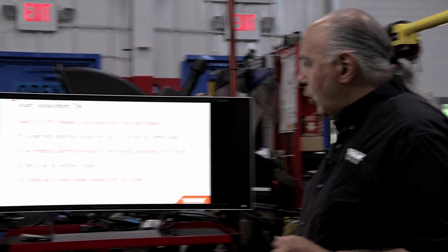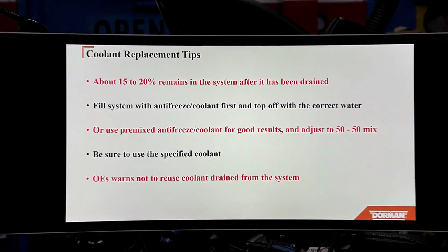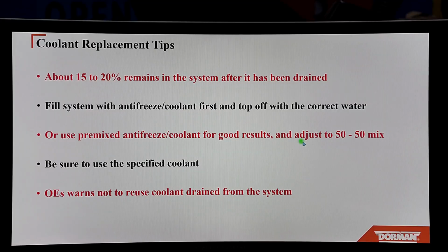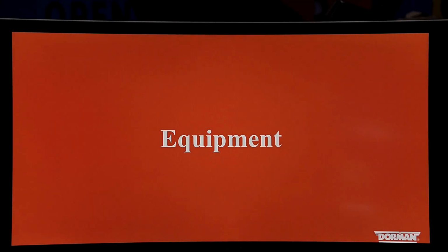They'll have the right water in there if you go by the spec. Or use premix coolant, antifreeze for good results, 50-50 mixture. Be sure to use specific coolant, they just said that. OEs warn not to reuse any coolant drained from the system. So you don't want any acids or problems, right?